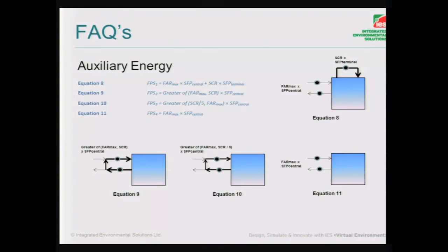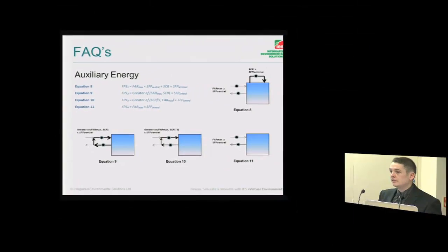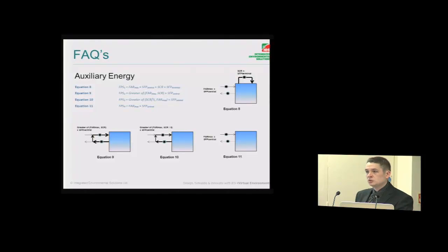In addition to this, we'll also have pump power that gets added on, and that's simply taken from a table in the NCM modelling guide and varies depending on the types of controls, whether you've got multiple pressure sensors in it or not, or I think there's about 3 or 4 different VAV pump configurations, and also whether the building has heating only or heating and cooling. But that's just a fixed value that gets employed. And it's also worth noting that the value the notional building uses is again the top level of specification that you can select. So again, there's not really any scope to improve upon the notional building settings.